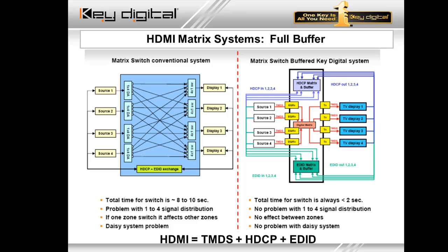I need to adjust my EDID outputting, or I need to adjust my output based on the incoming EDID from this display, considering all displays that are viewing me. This takes time. Usually it's approximately 2 seconds per display for this source to calculate and determine what it's going to output to accommodate X amount of displays viewing it.